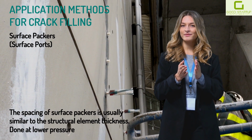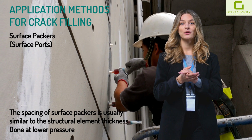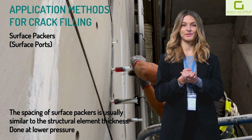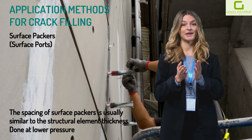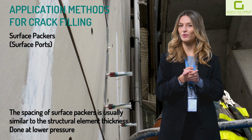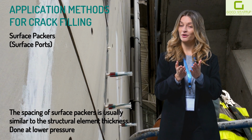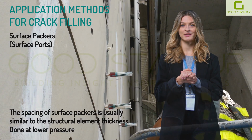The spacing of surface packers is usually similar to the member thickness. They're placed closer together than drilled ports because resin must travel within the crack from port to port. Surface injection is done at lower pressure compared to mechanical packers to avoid dislodging the surface ports or the epoxy seal, but it can effectively fill cracks in cases where drilling could damage reinforcement or where backside access is limited. This method is commonly used for narrower cracks in walls or slabs where drilling holes might not go through, or in repair of historical structures to avoid drilling.